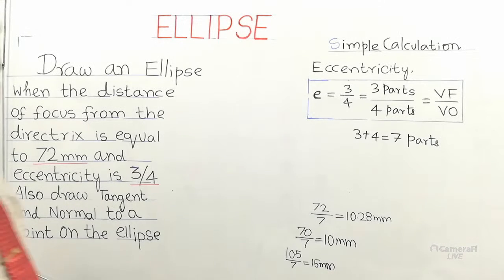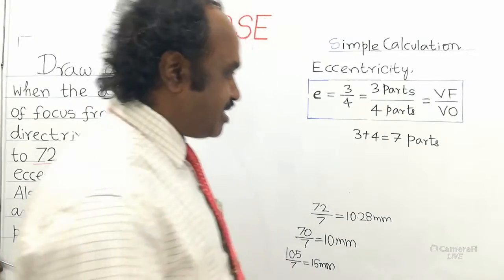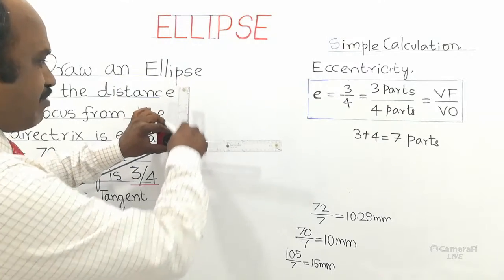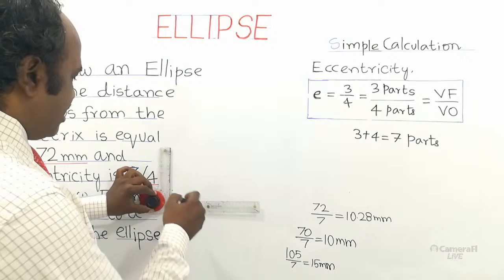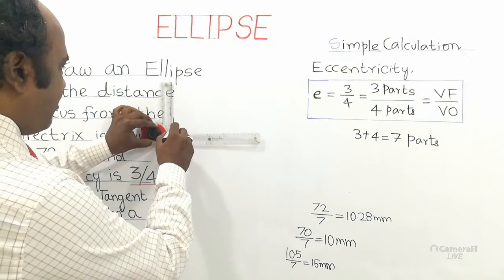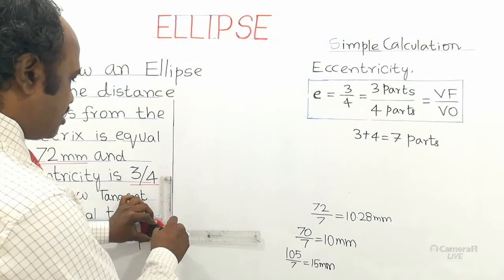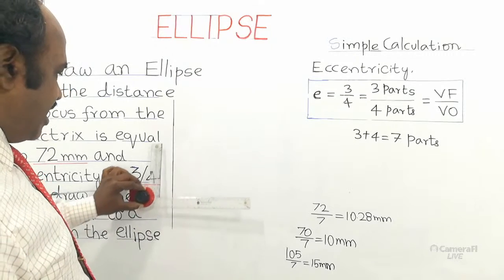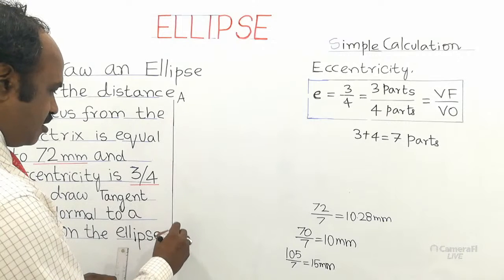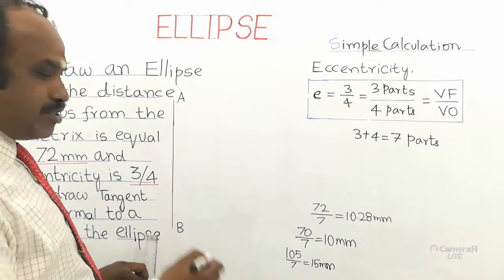So getting into the construction of ellipse, first you draw a vertical straight line called the directrix. Using the vertical scale of a drafter, draw a vertical line using your H pencil as a construction line, and the final curve, the ellipse, should be drawn in HB and appear dark. Understand? This line is called directrix, marked A and another end B. The length of the line may be of any suitable distance.